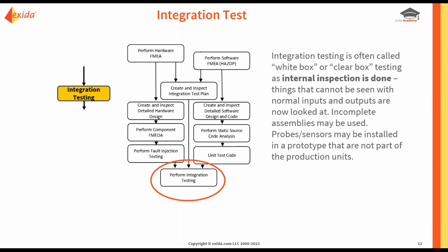And the primary objectives of integration testing are to verify, as I say, interface compatibility, ensure that your power supply has the correct voltages and currents for the rest of the system. The next one is to detect integration issues, identify and rectify any problems related to the integration of software components or modules, such as data incompatibilities. The next one then is to validate the overall system functionality. Next is to evaluate fault tolerance, and then finally to demonstrate compliance.